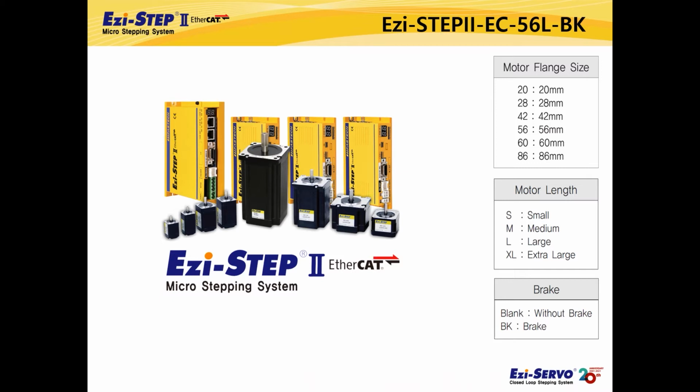In the example model name, EC means the product using the EtherCAT network, 56 means 56 mm motor flange size, and L means motor length. BK means that a brake is attached on the motor. You can select the motor from a NEMA 8, 20 mm size motor to a NEMA 34, 86 mm size motor.